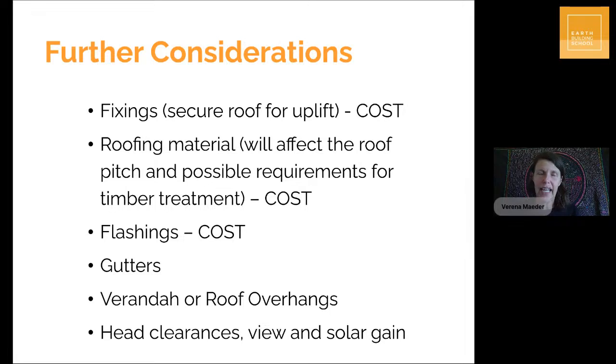And the other thing that adds cost are the flashings. So your decision on the roof shape will have a knock-on effect into costs. If you have a shape like this up here, where the sheets of roofing meet, you have to have a flashing. A flashing is a piece of metal that spans over changes in angles, changes in materials, and so forth.